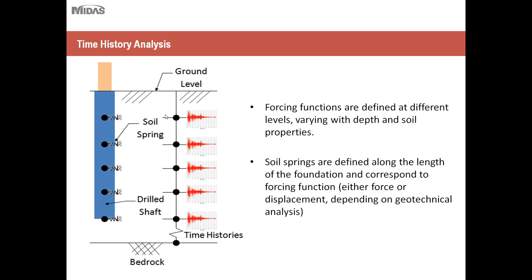So the soil springs are defined along the length of your structure, and depending upon which soil layer it's pressed up against or in contact with, the properties of the springs will differ. So beforehand, typically what engineers do is they'll have their damping coefficients created for each of their soil layers.